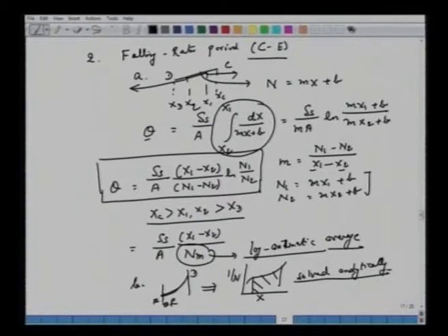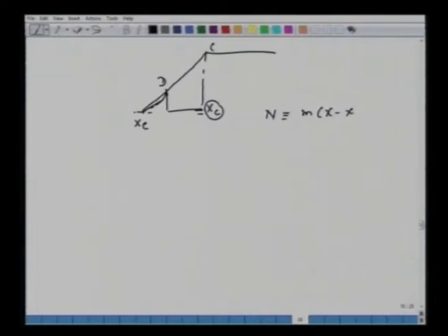All right, very often one makes an assumption that after this constant rate, which starts decreasing at critical moisture content, this curve goes all the way till xc. Now again, this depends upon the type of solid, where we can say that this region is quite small compared to the total region, total theta, or it's possible that there's not much change here whenever you have this inflection at d. In that case, one can make a linear assumption right from here to here to say that the rate is an approximation. This is m, the slope of the curve, x minus x star.